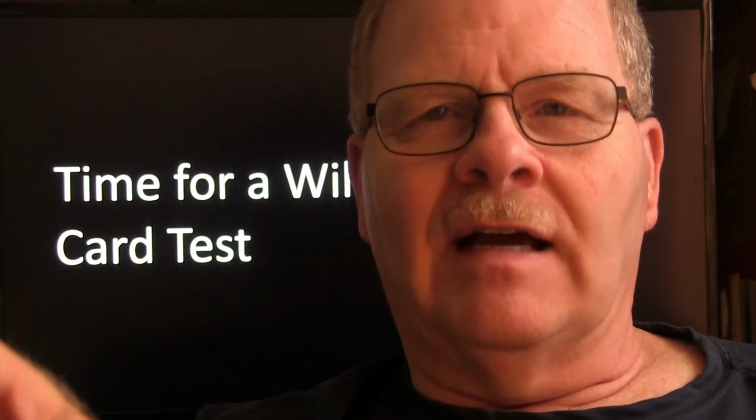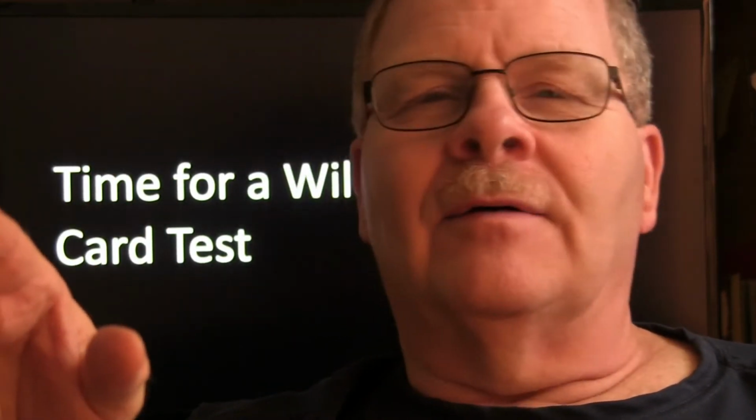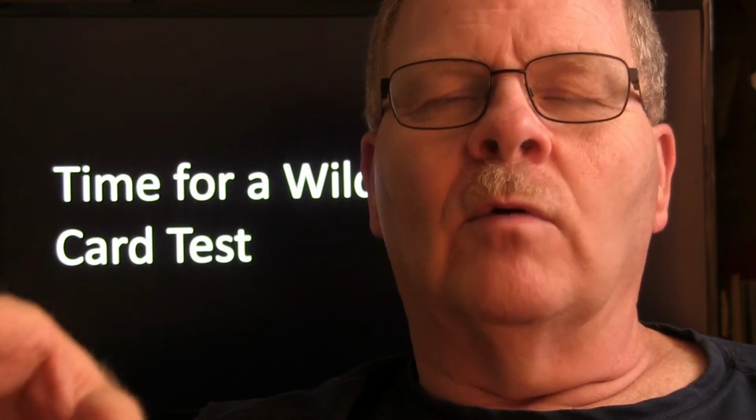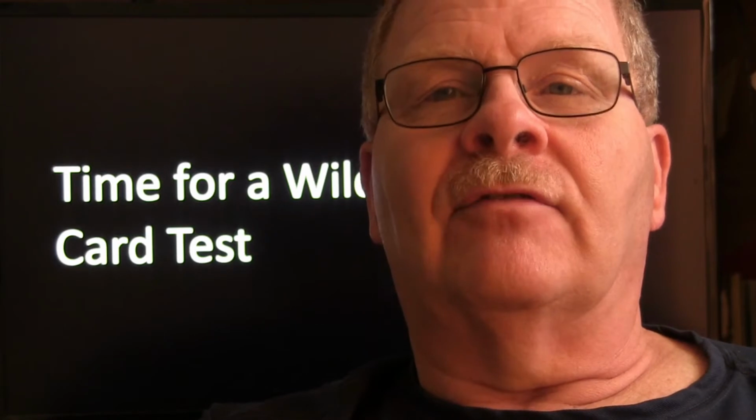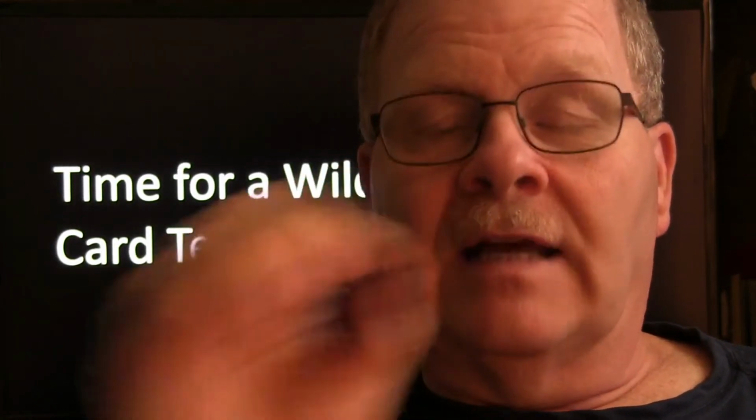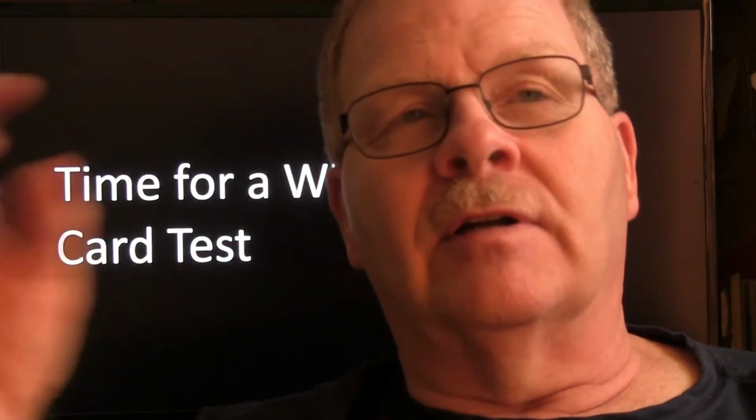But there was another one that came from the chicken plant. He said, this engine has a burnt valve. And we know it's got a burnt valve, and we know which cylinder it's on. They need this thing back this afternoon by 4 o'clock, and right now it's 10 o'clock. So we need you to pull the head off and take the burnt valve out, put a new valve in there and lap it in. We just need you to do that one valve.